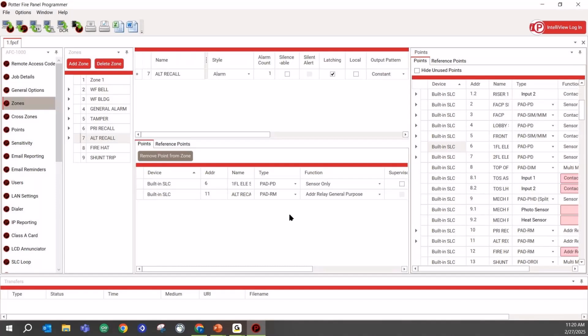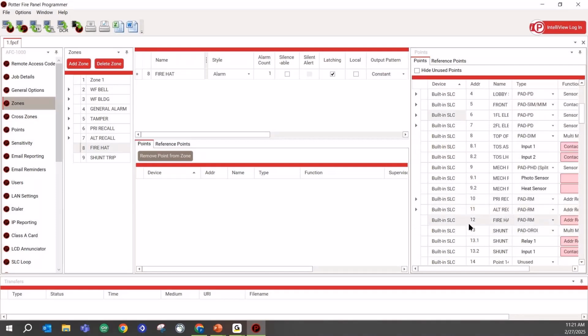So now stepping forward to the fire hat, please keep in mind not all elevators are the same, but in my experience, if the fire department arrives, they're going to put that elevator back in service. And that is because fire hose is not light, so they're going to take that key and they're going to put that elevator into firefighter operation mode. When they do that, that fire hat light is going to come on solid, indicating that the elevator is in firefighter operation mode.